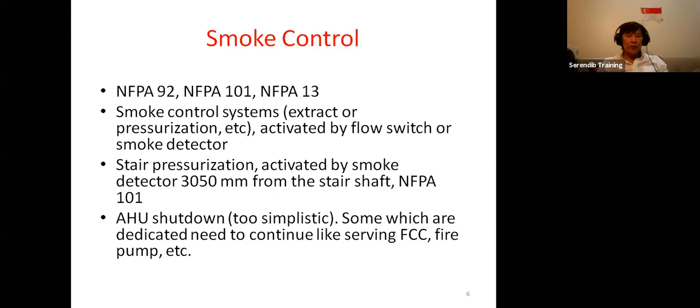Sometimes I get into commissioning, but the other part of my role is to make sure all fire safety systems interact with each other in a sensible, correct way. If systems have been done differently from NFPA, then I have to put my fire engineering knowledge into practice to make sense out of whatever has been deviating. Usually not too much. The deviating part usually leads to whether the first knock brings up the alarm or the second knock. But this will bridge the gap between what the NFPA requirement says and what has been done at site.